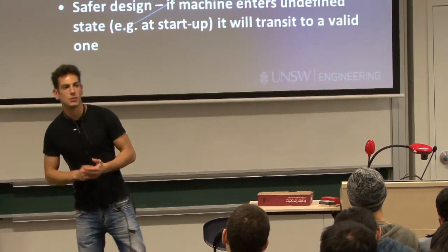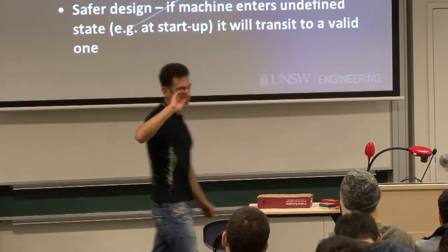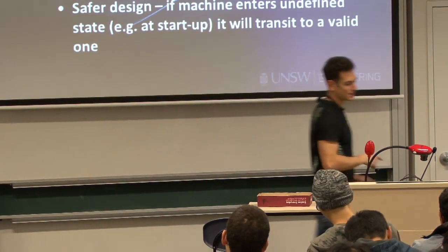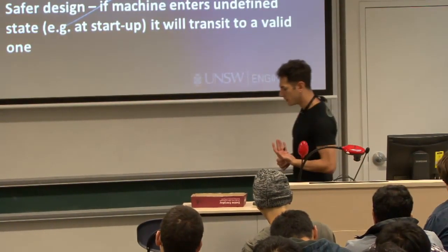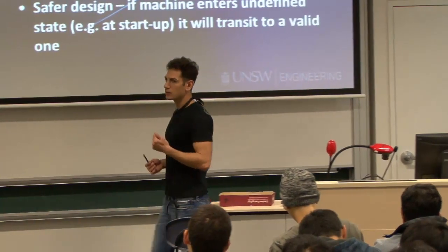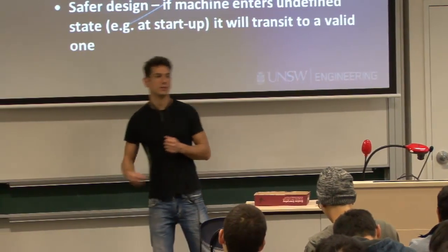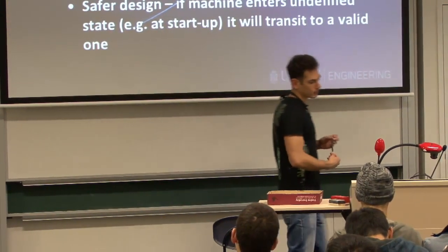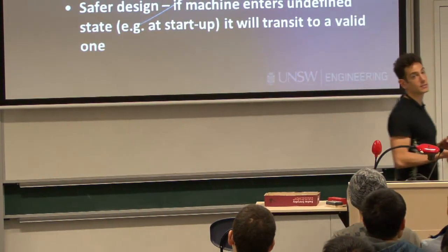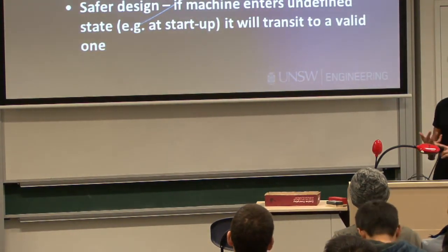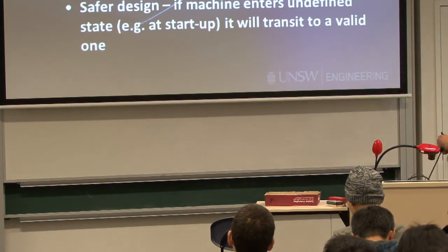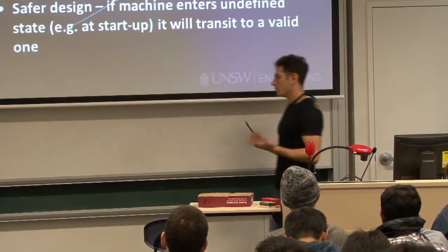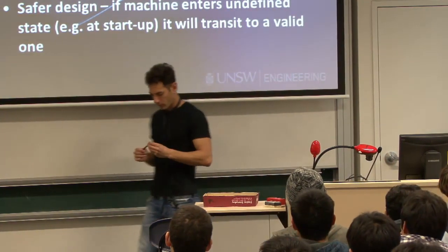There's no way a state machine will sort of say, okay, I had enough of this, I'm going to one of the unused states. But usually we might get into an unused state if we start up the circuit and we don't take care to actually reset the values into the flip-flops using either a synchronous or an asynchronous direct signal. So again, depending on what you're working with.